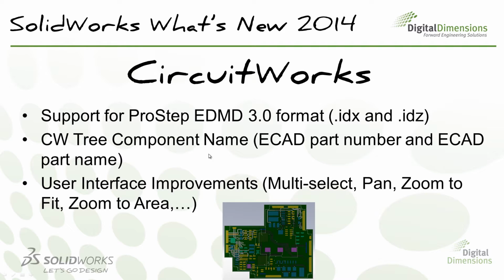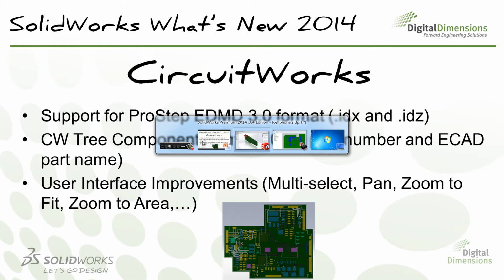So one of the last couple things I want to show you is that when you're sorting through your information, when you're looking in CircuitWorks, you can tell it to show the sort by ECAD part number or by ECAD part name. So you can sort differently when you're actually opening up these files. So let me show you where that setting is in CircuitWorks.